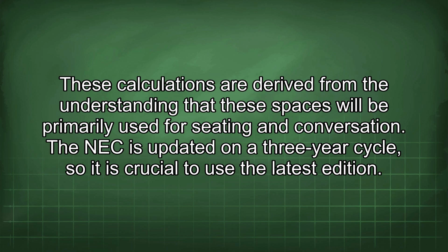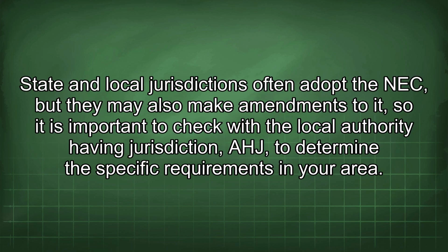The NEC is updated on a 3-year cycle, so it is crucial to use the latest edition. State and local jurisdictions often adopt the NEC, but they may also make amendments to it, so it is important to check with the local authority having jurisdiction, AHJ, to determine the specific requirements in your area.